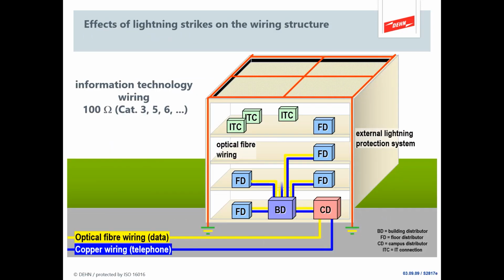So here we have a structure which has got a network system inside. It's got lightning protection on the roof, and lightning hits the roof. The lightning does what we want it to do, which is it goes down the conductors into the ground, but also the mesh on the roof is energized. And any cable within influence of the mesh on the roof or the conductors will have a small induced current going down those cables, which could take out the rack mounted hub or switch.